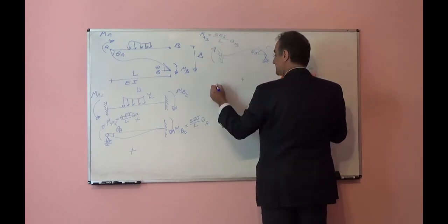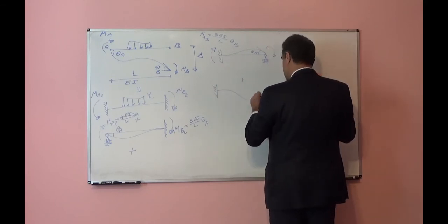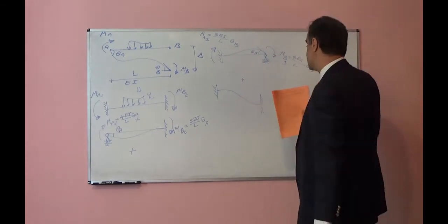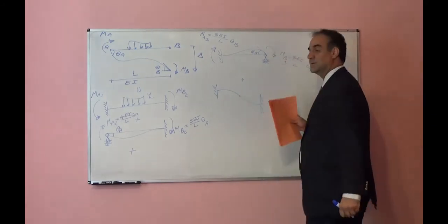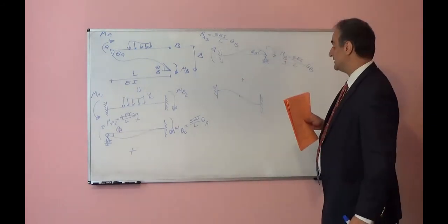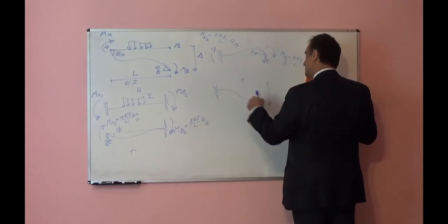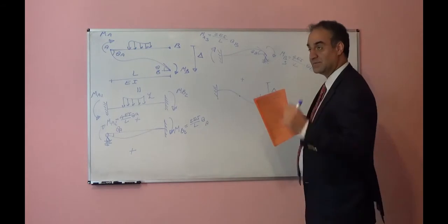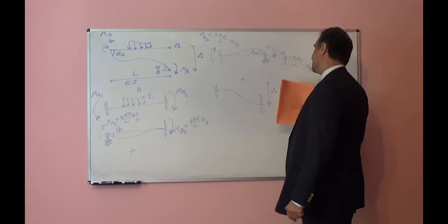And the effect of lateral deflection or settlement, I calculated, and you see in one point, because it is symmetrical, that point will be exactly in the middle. If total settlement of A with respect to B was delta, at the middle that will be delta over 2, and we will have an inflection point at the middle.